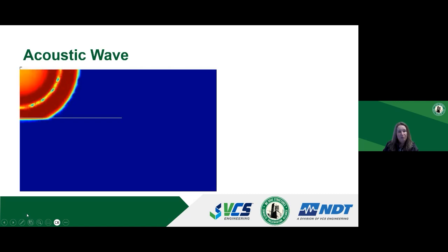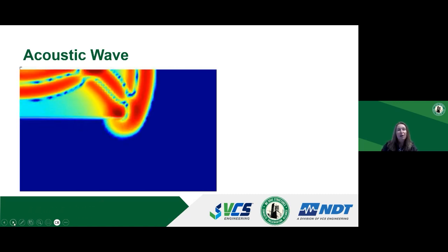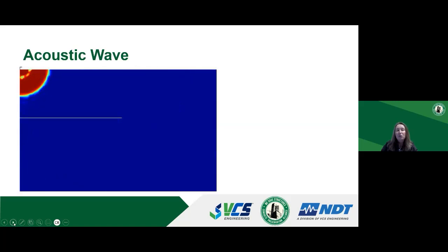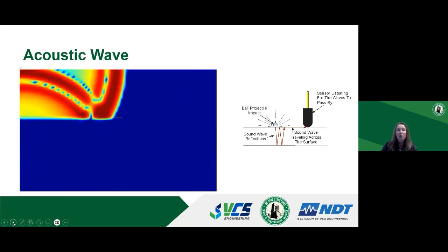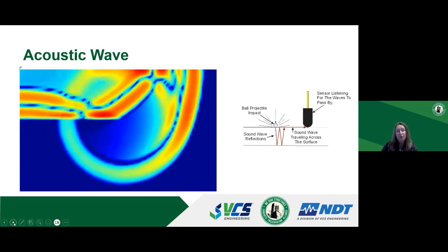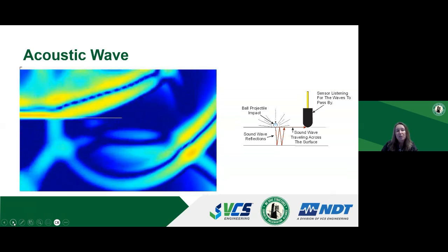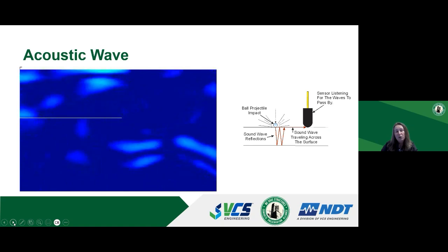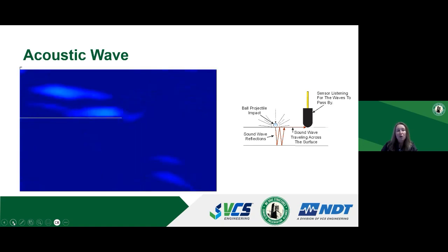This video illustrates how acoustic wave travels through the concrete and the effect of a defect on the travel path of the wave. The defect in this video is indicated by a horizontal white line. And in a real structure, this can be a crack, a delamination, or a void in the concrete.